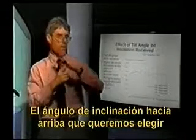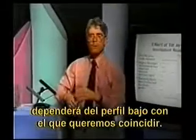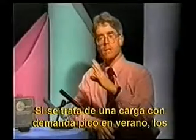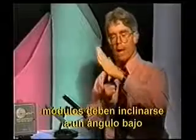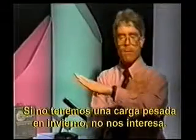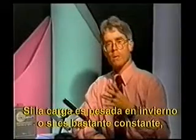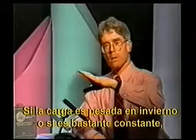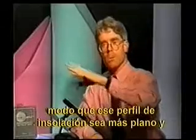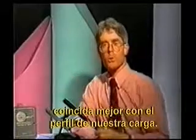The tilt angle that we want to choose is going to depend on the load profile that we're trying to match. If we're trying to match up to a load that has a peak demand in the summer, we want to have our modules tilted to a low angle that favors the high summer sun. We don't have a heavy load in the winter, we don't care about that. If our load is heavy in the winter or is a fairly constant load, then we'll want to tilt our modules up from the horizontal so that that insolation profile is more flat and is more appropriately matched to our load profile.